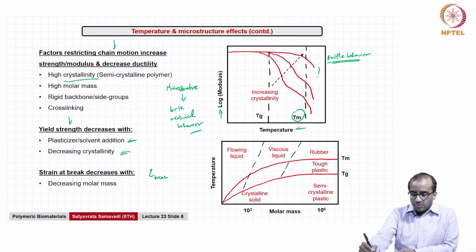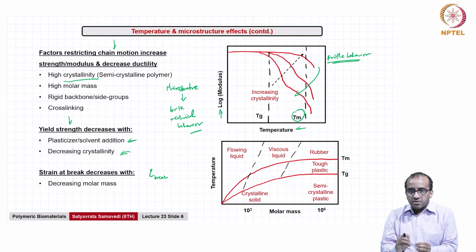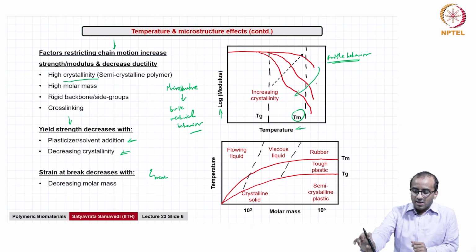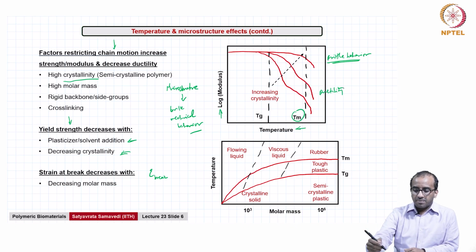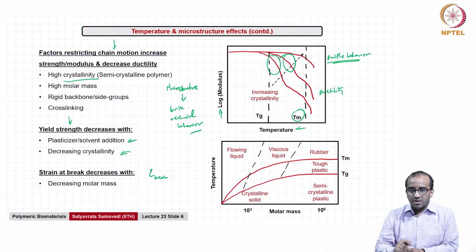But as you come down, as the crystallinity decreases, the introduction of the amorphous domains is now going to lead to ductility or ductile behavior. And the other point to note here is, as that happens, because you have these amorphous domains, you see a second transition happening close to the TG for these kinds of materials. So again, 2 points here as well.